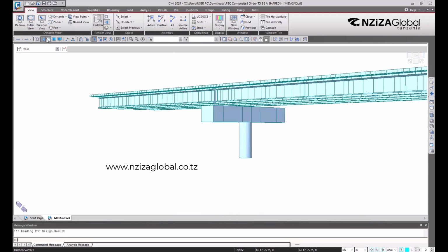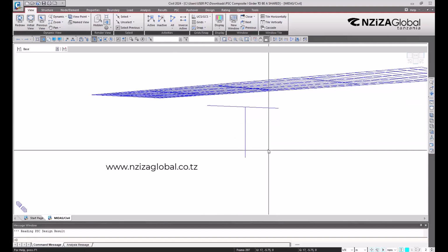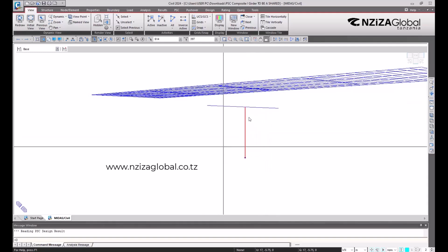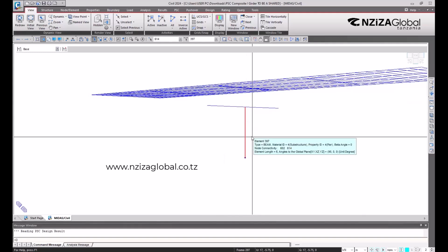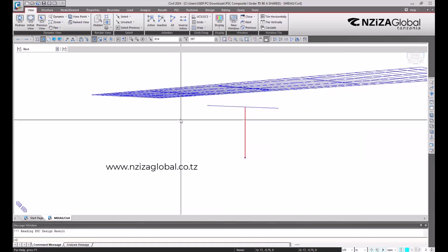Okay, let me put in line mode. You see, when I do like this, this top solution is not selected. But when I select this, like this, no matter what, selecting in AutoCAD, you know, when you come from left to right, only the elements covered by the selection will be selected. But when you start from right bottom, then you come crossing the object to be selected. The same applies.